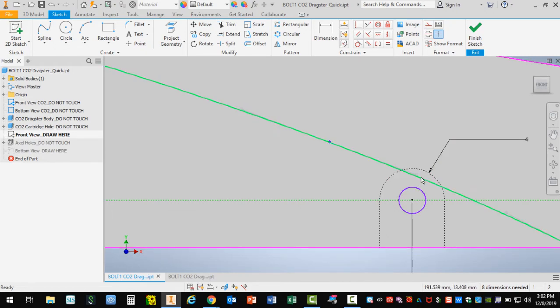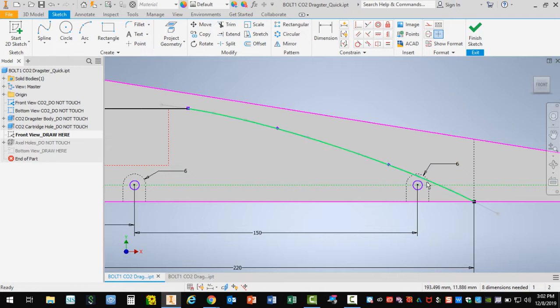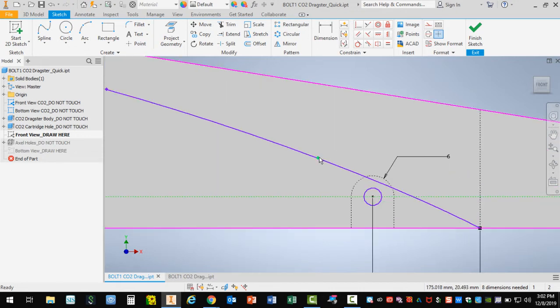So obviously I drew through this half circle that you can see here. So let me show you how to change that. I'm going to go ahead and hit my escape key just a few times to get out of the spline interpolation tool. So what's great about this function is I can click and I can drag these points. As you can see here, I can left click and drag, and that way I got outside.